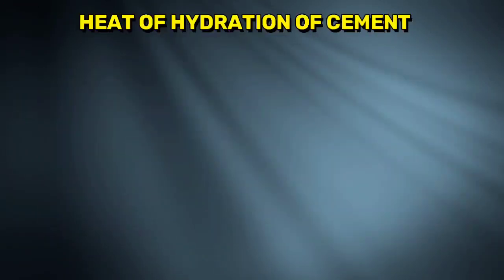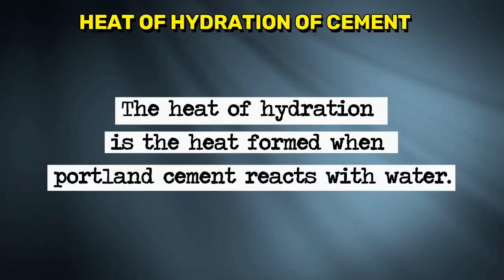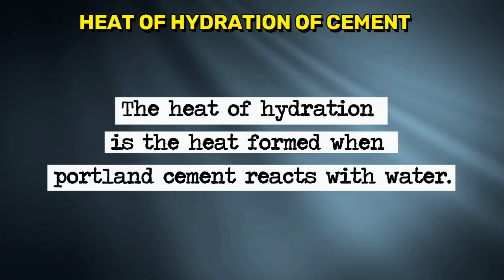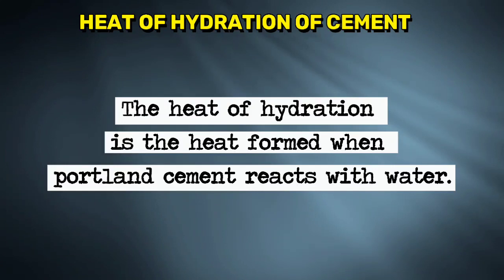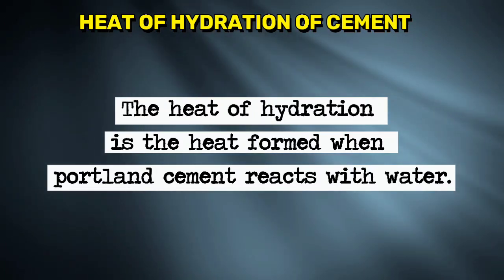So we could actually look at the heat of hydration. All right, the reaction of cement with water is exothermic, as I've said earlier, and the reaction liberates a considerable quantity of heat. This liberation of heat is called heat of hydration, and it's clearly seen when freshly mixed cement is put in a vacuum flask, and then the temperature of the mass is read at intervals. You could add this as a practical way of investigating the heat of hydration.